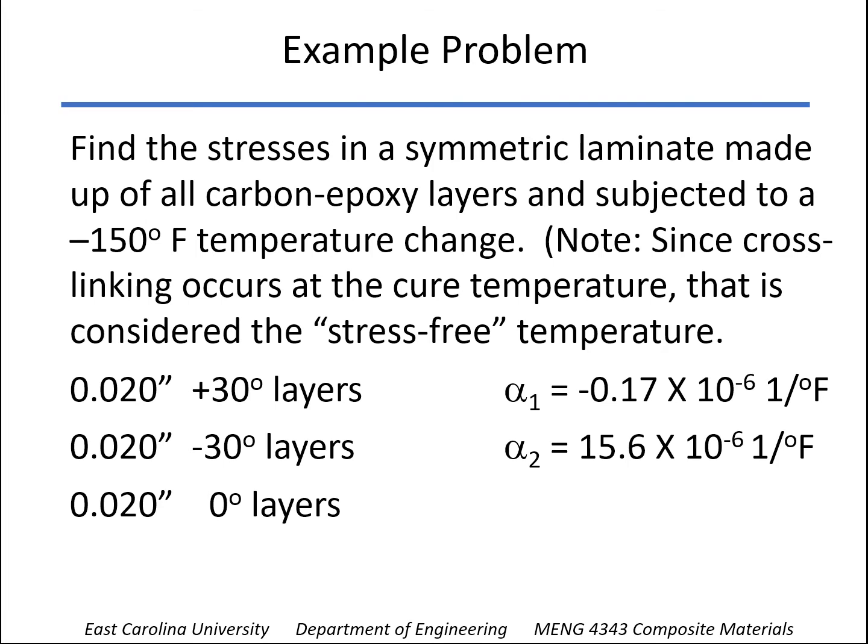As we noted last time, it's pretty typical to have a negative temperature change. If you cure at an elevated temperature, then you have the resin kind of flowing until you reach that temperature, but then the cross-linking occurs up at that elevated temperature, and that becomes the stress-free temperature. So when you cool back down to room temperature, you lock in some stresses, and that's what we're going to